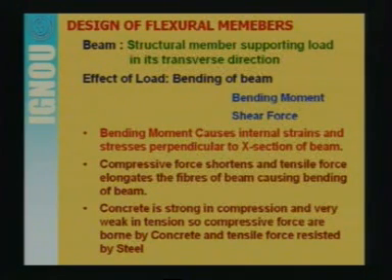Now, as you know, concrete is strong in compression and very weak in tension. So, the whole of the compressive force we try to have the concrete take, because it is weak in tension. What should be there to resist the tensile forces? To resist the tensile forces, we use reinforcement or steel. So, steel is used to resist the tensile forces and concrete is used to bear the compressive forces that are developed in the beam.